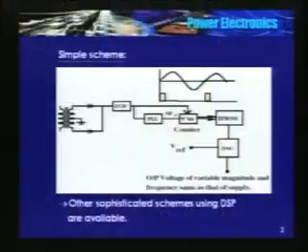I will explain the working of this circuit very briefly. So what I did is I took a sinusoid, a center tap transformer, I rectified it, okay, a full wave rectification here. Then I gave it to a zero crossing detector, nothing but an op amp. Then I got 2 pulses here at the zero crossing.